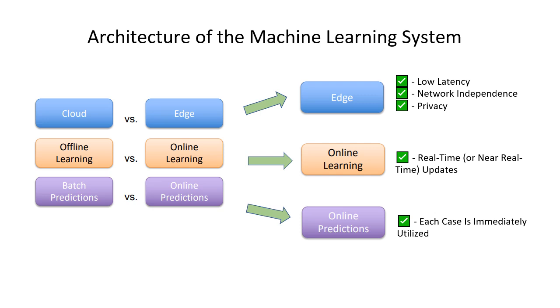Online predictions versus batch processing. Online predictions were chosen over batch processing. The inspection process must detect defects in real time, ensuring defective products are immediately removed from the production line without delays. This is critical in case of systematic errors in production that were not detected in the initial training phase. The system does not need to wait for image batches and can continuously improve with each new image.